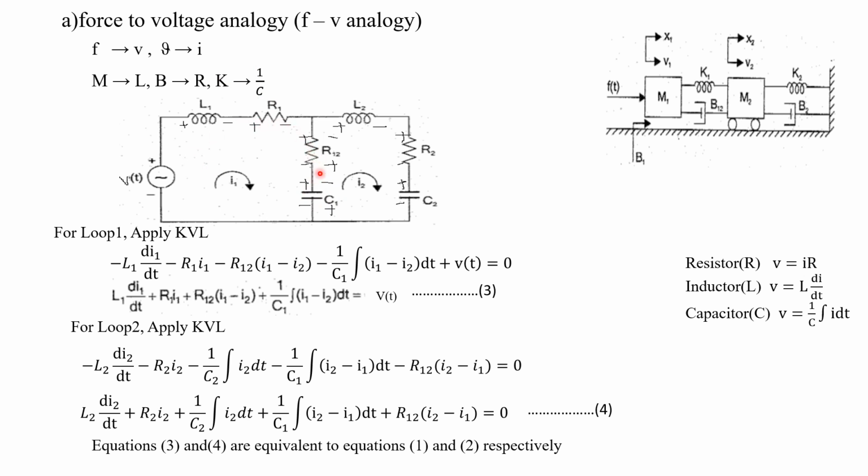In this way, we can represent all the elements of mass M1. So this will be represented in the first loop. While representing each and every term for the mass M1, the elements which are connected only to this mass M1 will be represented here, as well as here, in these two branches. And the element which is common to M1 as well as M2 will be connected here. So this is the common area to loop 1 as well as loop 2. Here you have to represent the common elements. Understood? No need to draw any elements here because this is a ground.